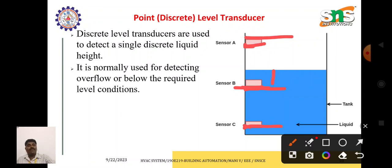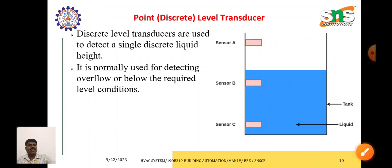If the water is below sensor C, we can imagine the water level is going to run dry. So this is discrete: the tank is full, or 50%, or going to run dry. But in between we are not able to measure using this discrete level transducer.